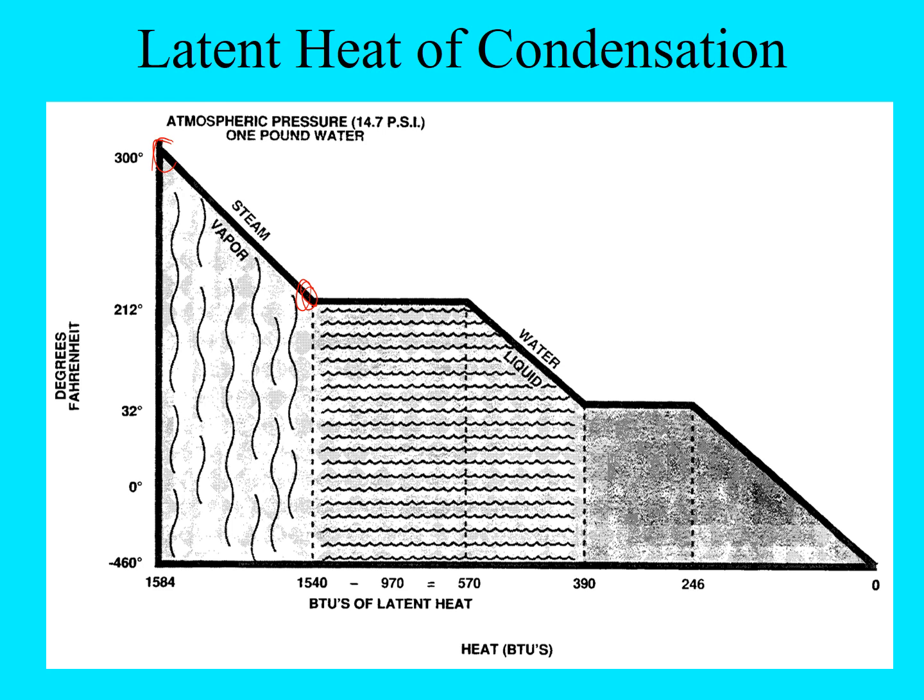Now we're going to remove heat out of the steam, and it's going to start to condensate completely into water once we remove 970 BTUs out of the steam.